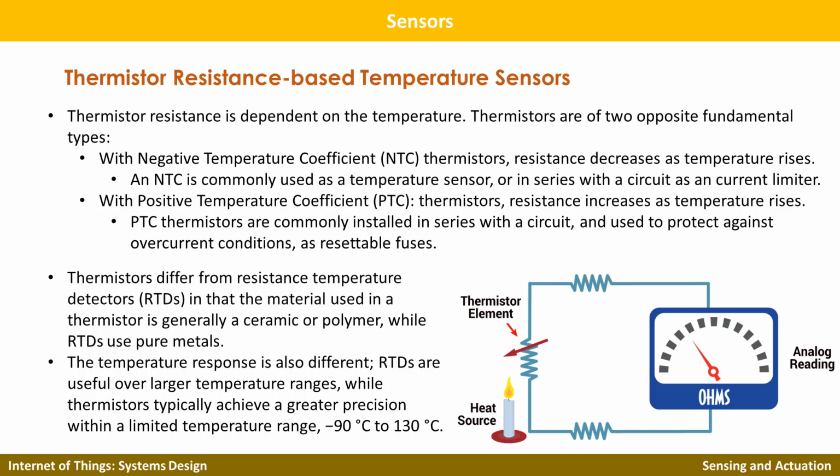In thermistors, the advantages are high output, fast response time, and high sensitivity. The disadvantages are that they are very fragile, non-linear, have a limited temperature range, and require a current source, because you need to put the current in and do the measurement. So if your application requires high sensitivity, fast response, and high output, then the thermistor would be the best option.